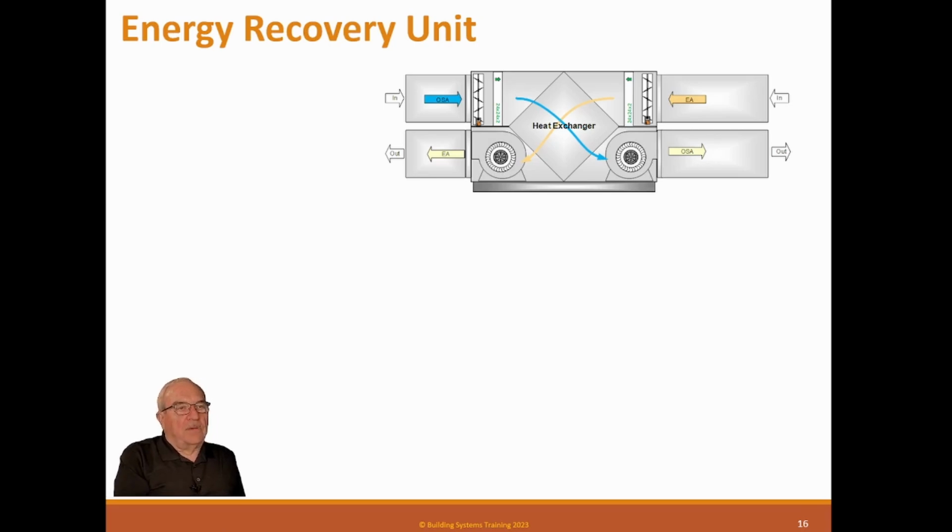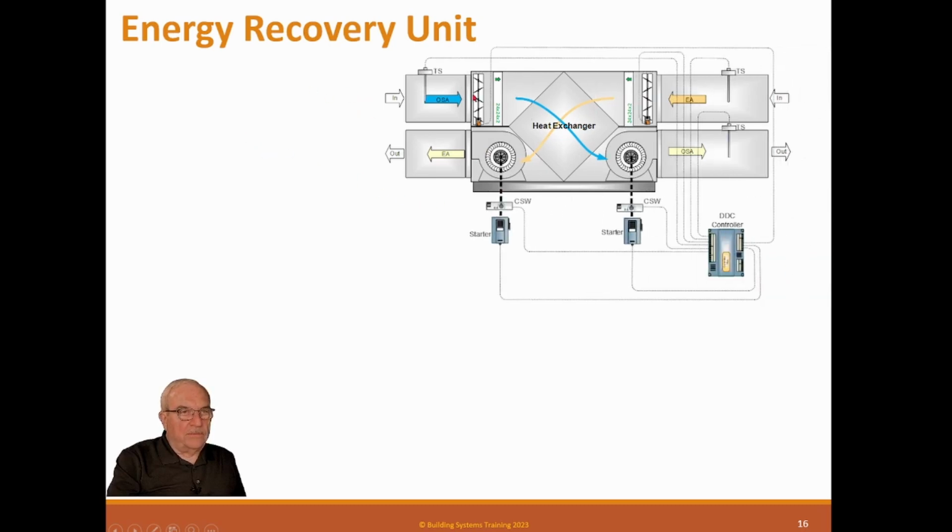All right, so now we're going to talk about outside air systems. So this is an energy recovery unit, and this is a really simple deal. You've got some exhaust fans in the building, or else this is the exhaust fan of the building, and it sucks air from those exhaust loads this way, and then we have an outside air load that comes in this way and goes to the makeup air units, the other units. So these normally don't do cooling or heating directly. They're actually feeding other units.